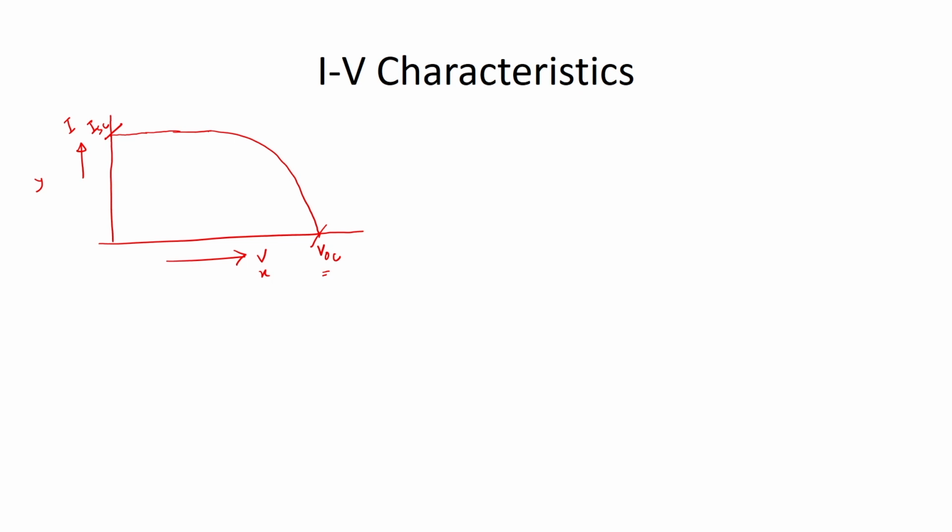In the same plot we can draw power versus voltage. If we are interested in power versus voltage, how will it look? It will increase linearly, reach a peak, then come down and reduce to a value of 0 at VOC.